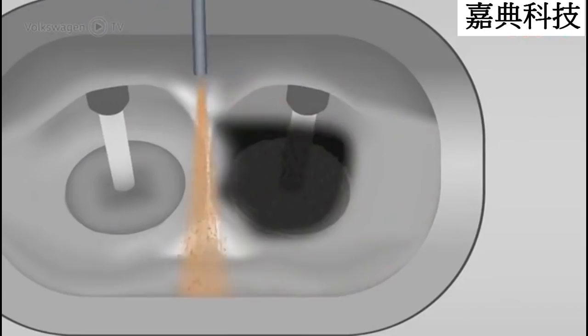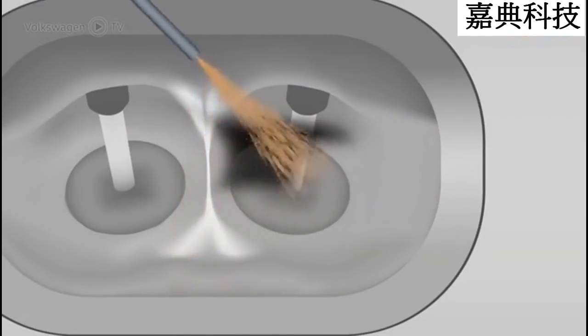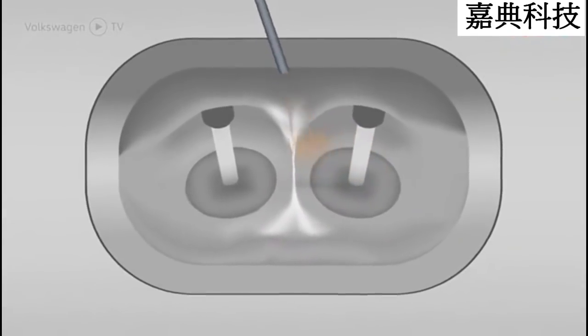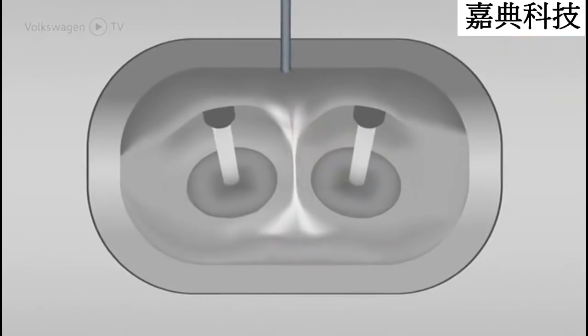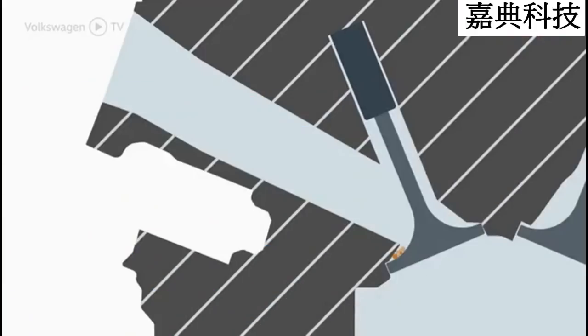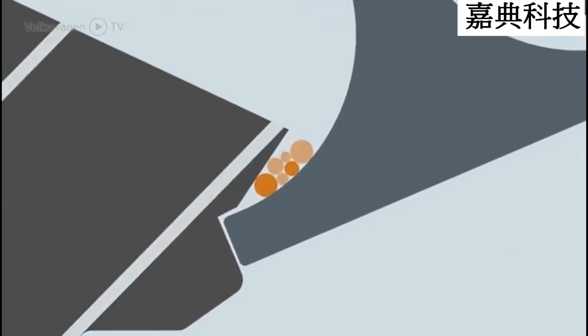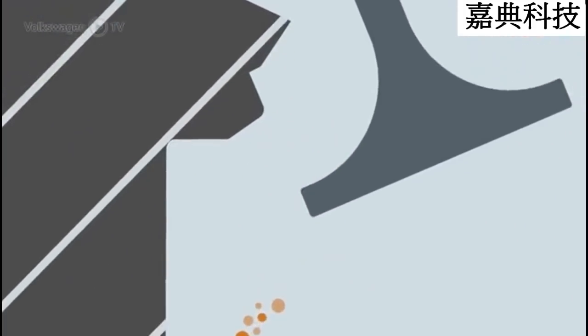Working with the granulate blasting unit means that you won't need any harsh detergents that could damage the valve stem oil seals. Even if small quantities of the granulate get into the combustion chamber, this is absolutely no problem.